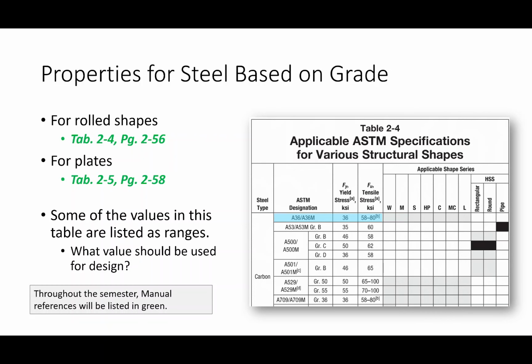So if you had a structure in a seismic region and you needed a lateral system to support the loads, you said, let's go with a moment frame. And the reason is that moment frames, and this is true, remember how we had moment frames and brace frames? Moment frames are more ductile. And ductility is important in an earthquake, so it made sense, okay?